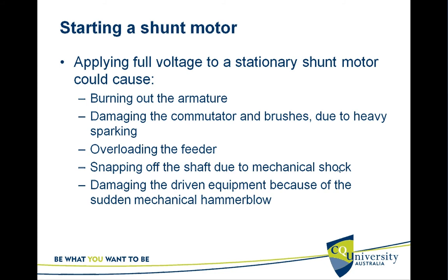Starting a shunt motor. How can you start a shunt motor? The tricky thing is, when you apply the full voltage, it could burn the armature, because there will be a very high current flowing and there is no back EMF. That's the trick.